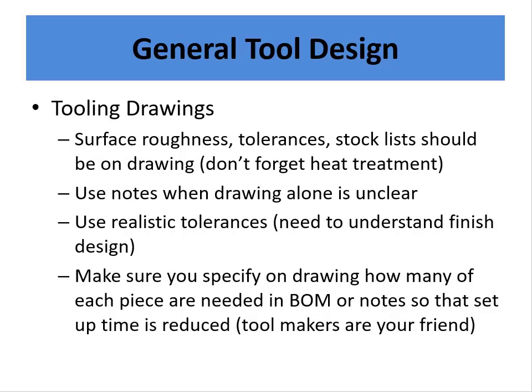And also, make sure, again, we cover this in CAD classes and in our drafting classes, but pay attention to this when you're doing tooling drawings. Things like your surface roughness and your tolerances and all this should be on your print. And if your drawing is not clear, make sure you do use notes. It's okay to use notes whenever they seem warranted.